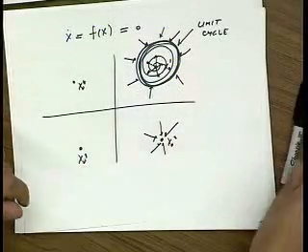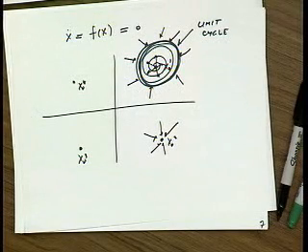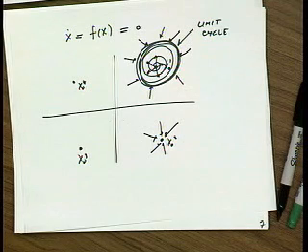Okay? So it seems like an oscillator looks like a feedback loop. When the amplitude goes up, you have more damping, the factor comes back, and so on. So can you characterize this with feedback theory, with response time, phase margin, and such? It's tough because it's not a linear system. So what you can do is linearize about a given operating point.